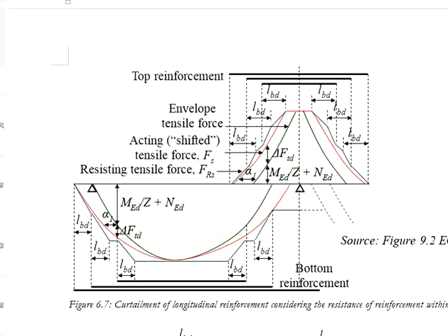Now, the same principles apply. This is applicable to 3 groups of reinforcement. Under some circumstances, you may choose to use 2 groups of reinforcement. You will adopt a similar process, only now your resistance diagram will differ slightly. Most likely it will be something like this. This will require you to do the calculations and work out the amount of reinforcement.